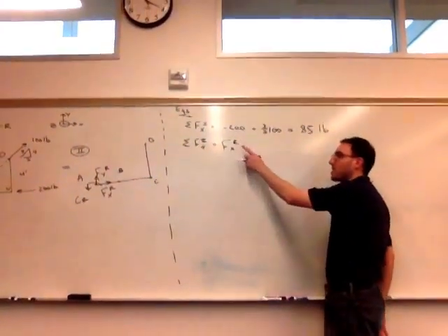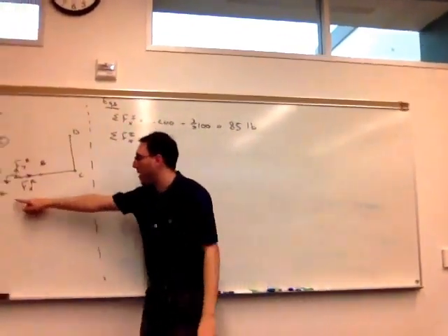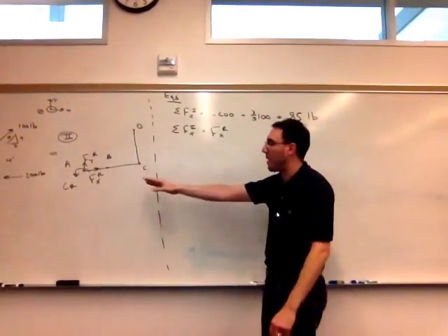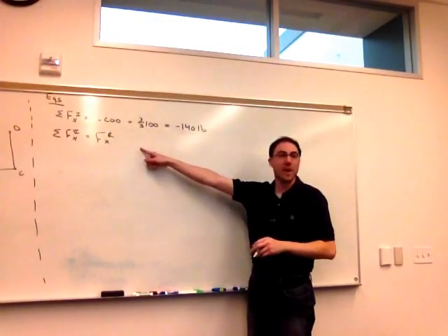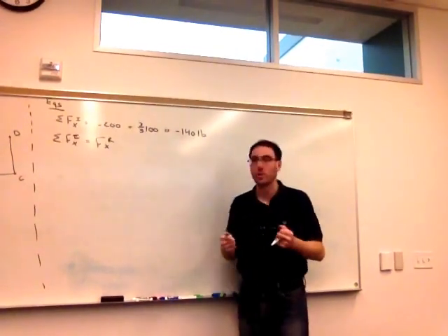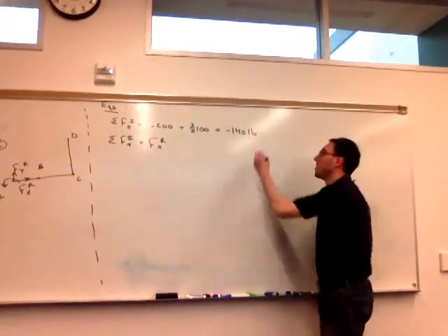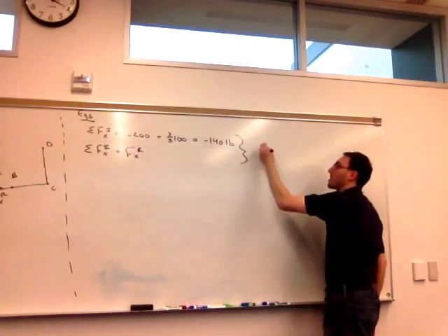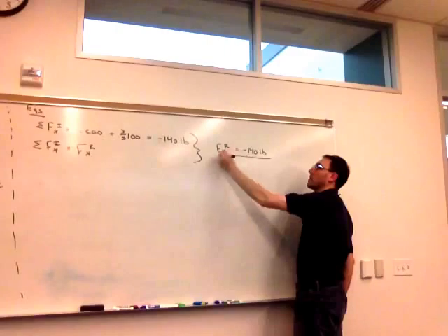So the only force in the x direction is FXR. And the couple, I'll point out, does not appear in our force equations. It's a couple. We'll get to it in a minute. Now we say, well, these are equivalent systems, so Fx1 must equal Fx2. So I equate this to this. Therefore, Fxr must be negative 140 pounds.